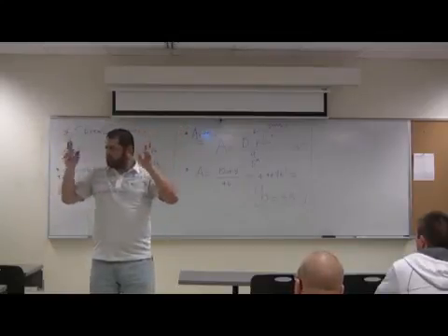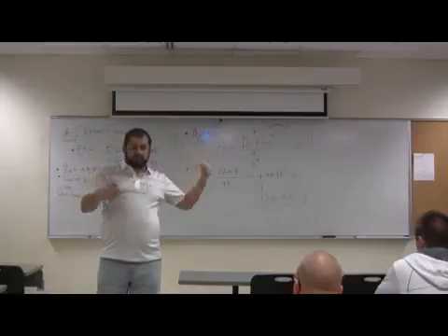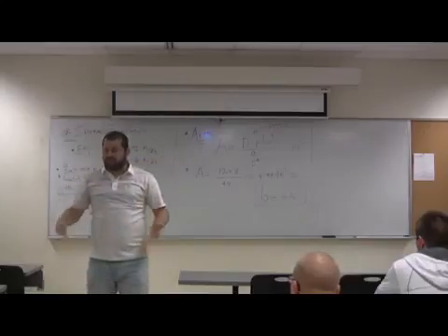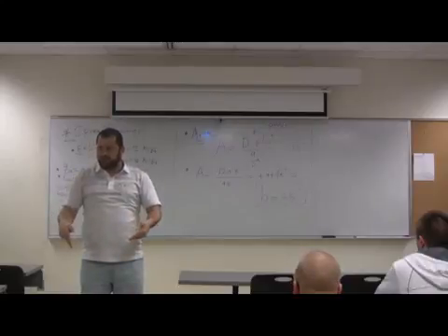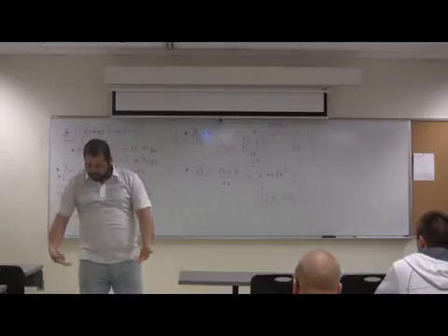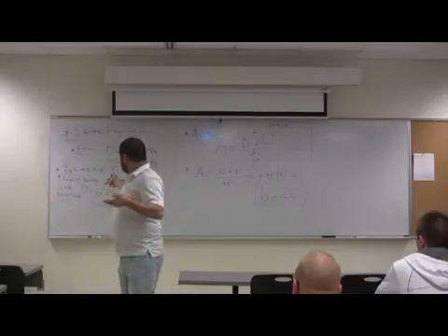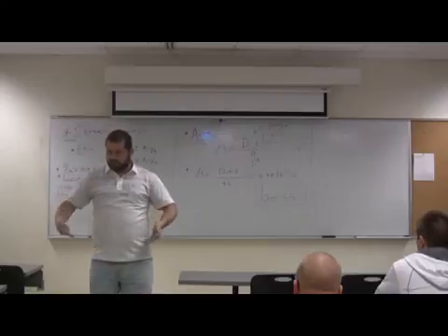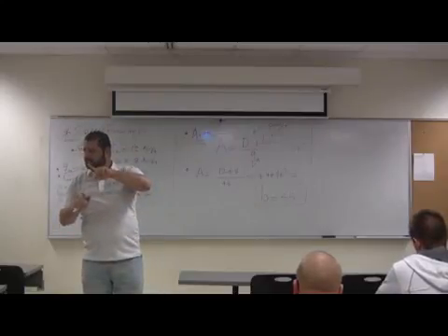Okay. You have two options. Either you add that as a load to this load here, or you subtract that from the bearing capacity. Because this will bring pressure on the soil, right? So the area between them is mixed with concrete and soil. How much? 4 feet. Let's assume one of them will be concrete, right? So how much is the weight of that 1 foot of concrete per square foot?